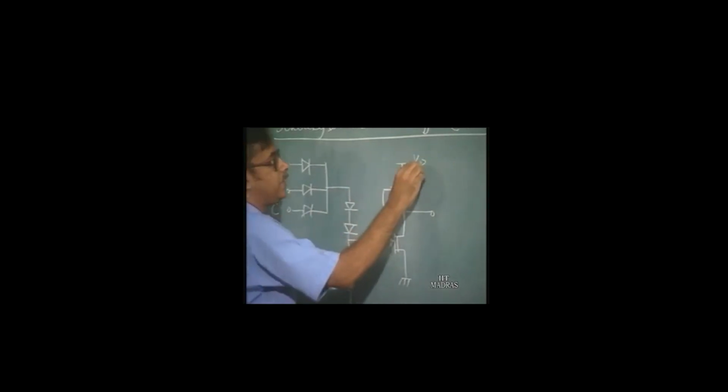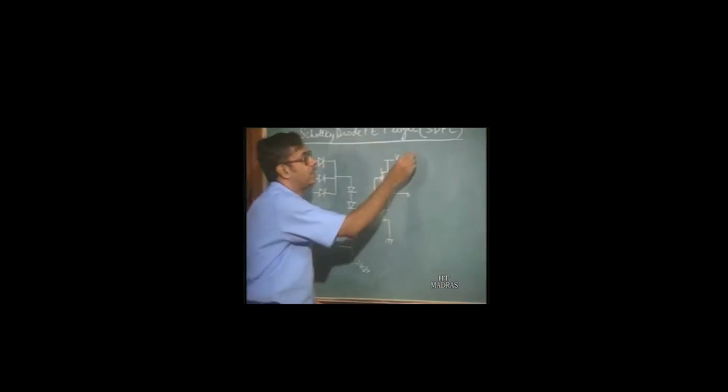So, this is VDD. Again you have a dual power supply as in the previous case, which is inevitable if you have an all depletion mode structure. This is one of the drawbacks of all depletion mode circuits. So, this is the inverter. Now, you have a logic section, followed by a level shifting section, and followed by an inverter.